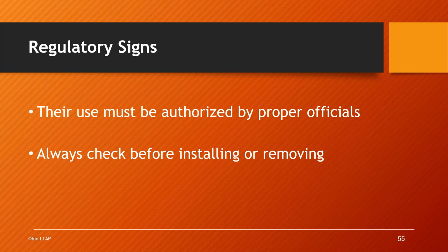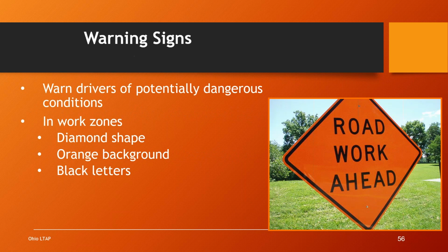So regulatory signs must be authorized by proper officials, so we always need to check before installing or removing. Like, for instance, no parking zones or something like that. You would need to make sure you cleared that with the city engineer's office or village engineer's office.